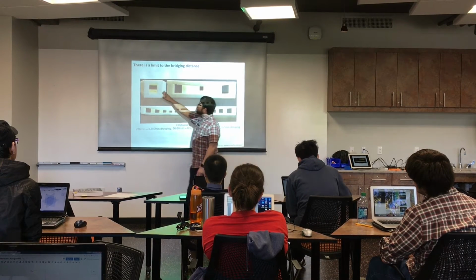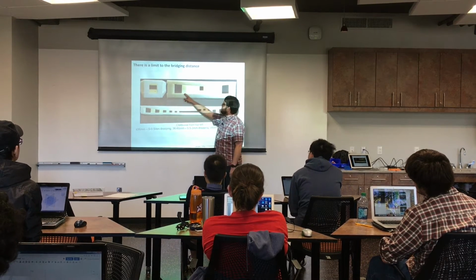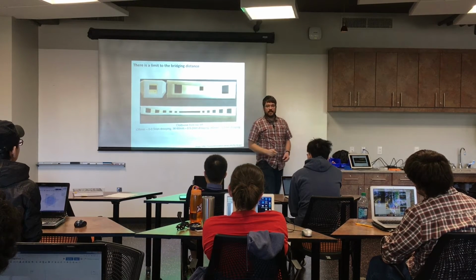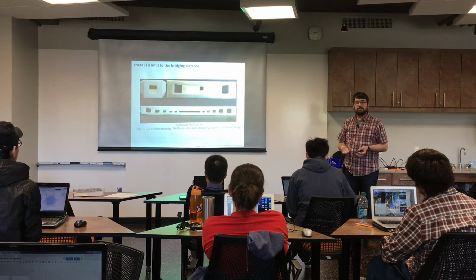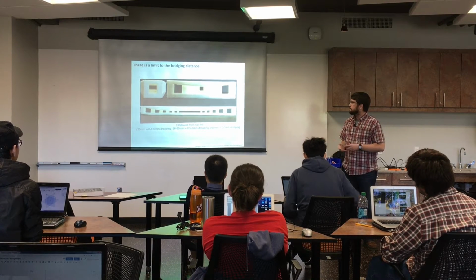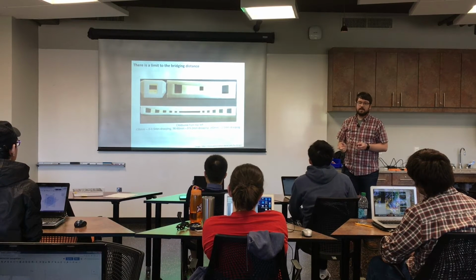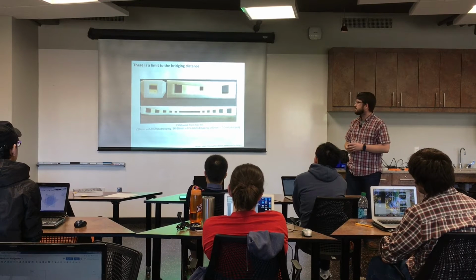You can see here on the narrow end where you're bridging maybe half an inch, it's fine. As you start bridging multiple inches, you start getting layers that don't adhere and start sagging. So you'd have to support that somehow, either with a permanent or a temporary support material. It just doesn't work if you try to bridge more than maybe a couple of inches at the most. And I think that's even kind of pushing it. I try to not do that.